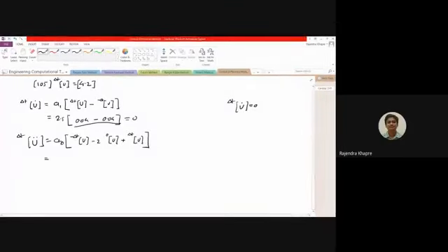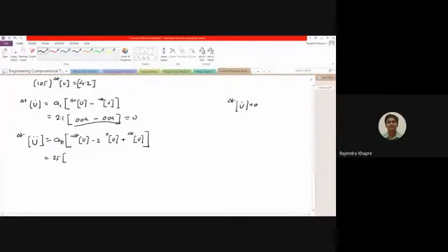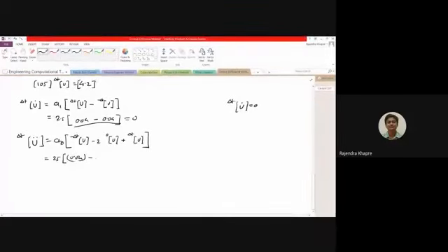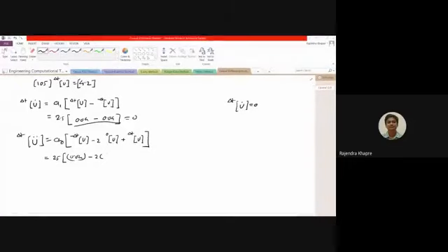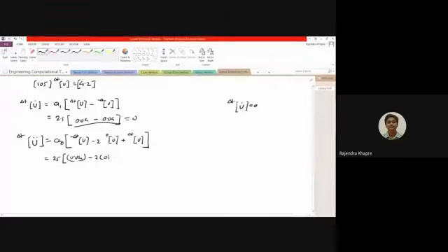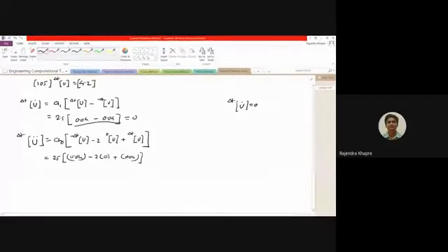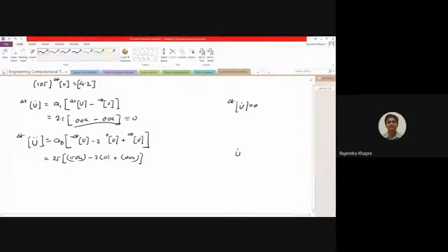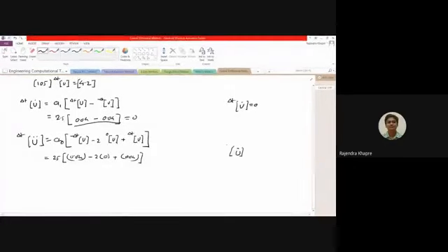If you substitute these values, a0 comes out to be 25. The displacement at minus delta t, we just saw, is 0.04. This is minus 2 times the displacement, which is already 0 in the initial stage, and plus 0.04, which we also saw. So with this you can now calculate the acceleration at delta t.